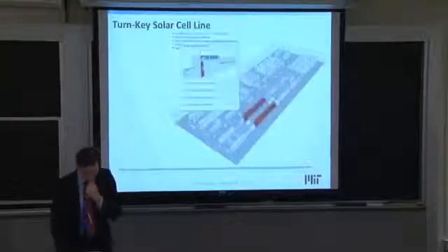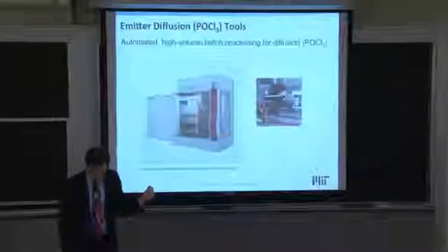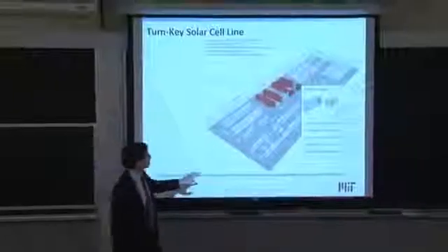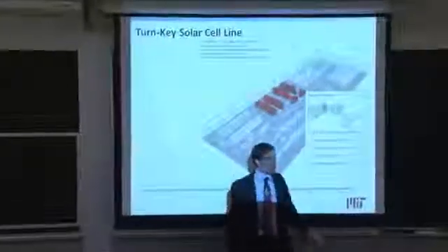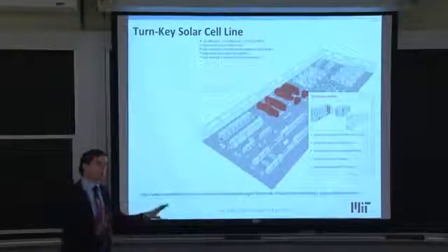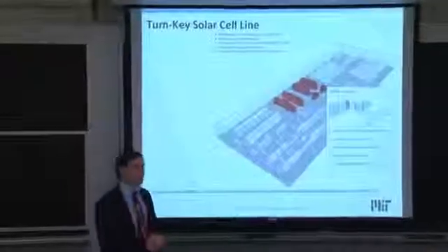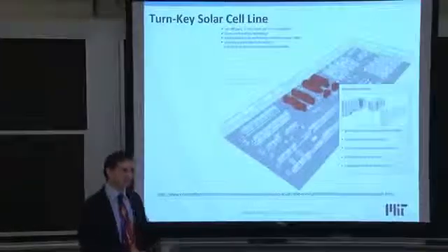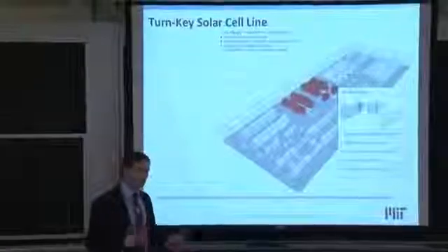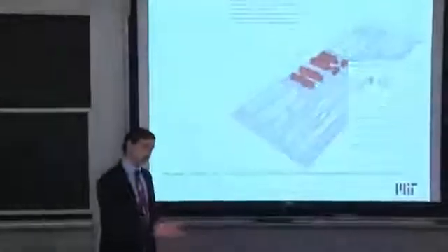Great question. So some of the earliest designs for the selective emitter, if we go back up to the selective emitter portion, used a photoresist process. But I would say nowadays there are a few technology options that are much faster, one of which involves creation of porous silicon on certain regions of the wafer that you want to etch back and create the shallower emitter, leaving the deeper region intact.